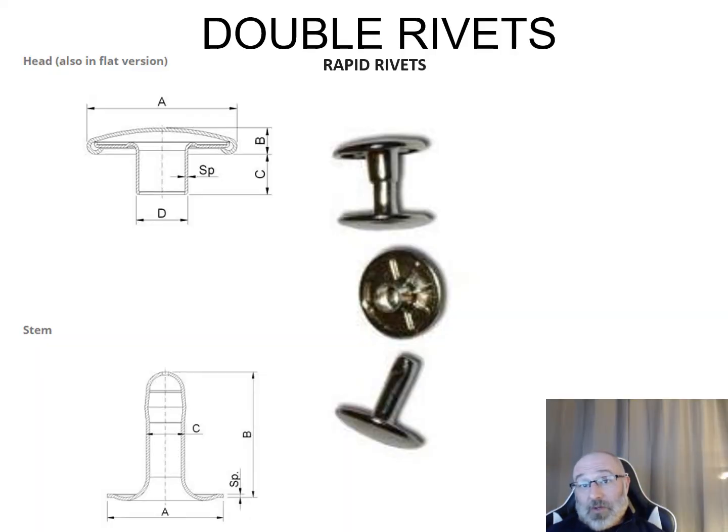Now with those tubular rivets, especially using the washers, they're not the easiest thing to install, especially if you don't have the appropriate and expensive tools and presses that are specially made. Every type of rivet takes a special die that fits into that press, which you have to have custom made for a lot of these. It can get expensive. It's not very portable. So there are other types of rivets that might be cheaper, easier to use, and more readily available.